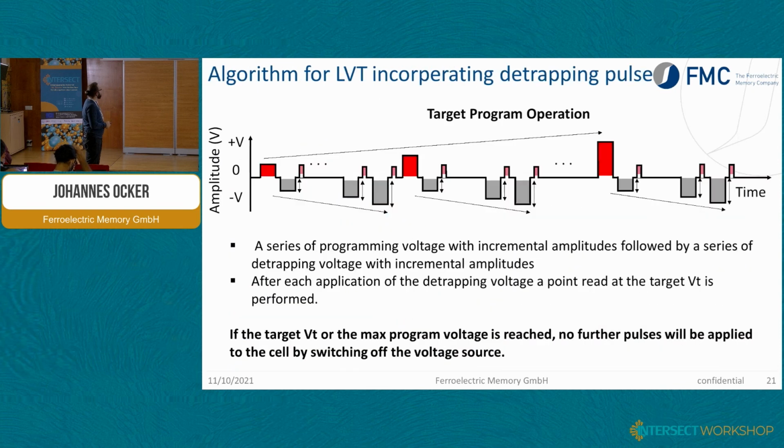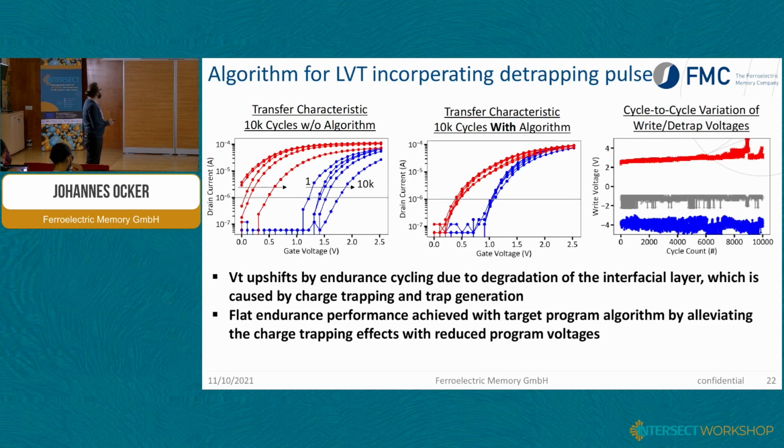This leads to a shift of the threshold voltage for both high VT and low VT to more positive voltages. With the algorithm, we are able to fix all that: if it is continuously charging up, we just apply larger detrapping voltages. So problem solved, no? But it is very important to really understand what could be the physics behind all these experiments.